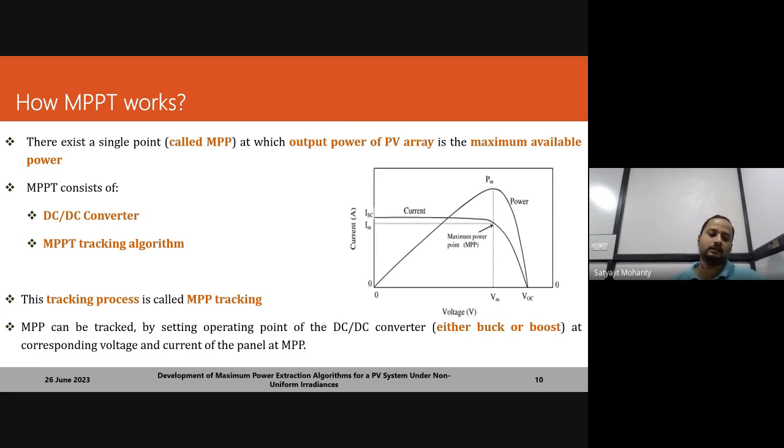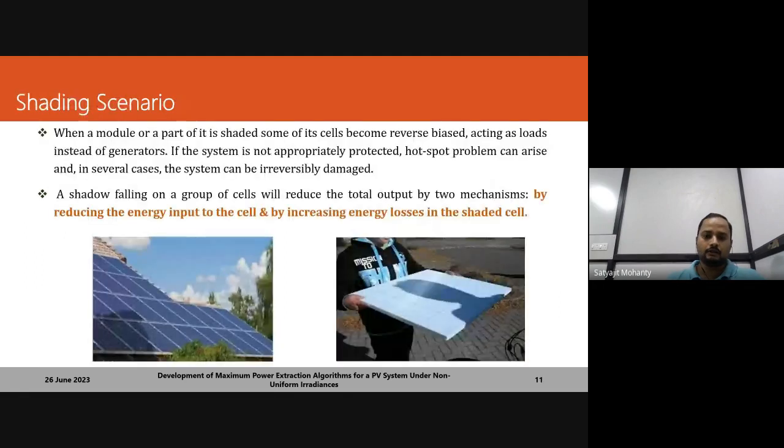Normally, in such scenarios, clouds play a great role in creating disturbance in the process of generating maximum power. These are the scenarios that may arise. Regularly we need to clean the panels, every 15 days or one month, using some liquids so that the dust gathered over here is eliminated and we can generate the maximum possible power.